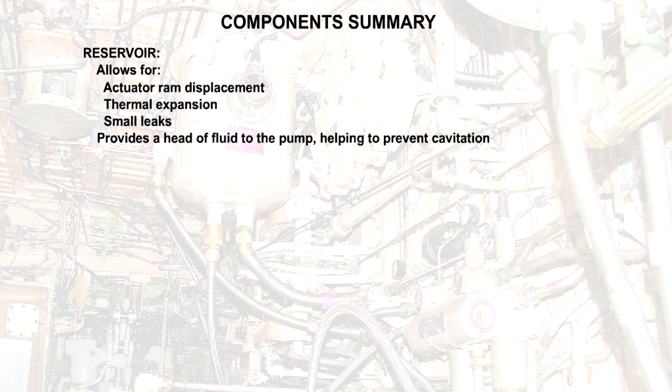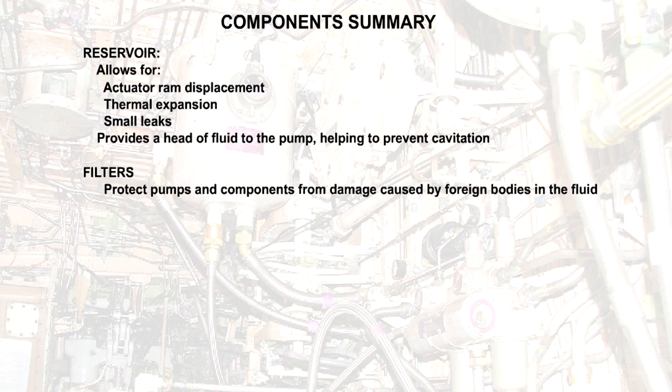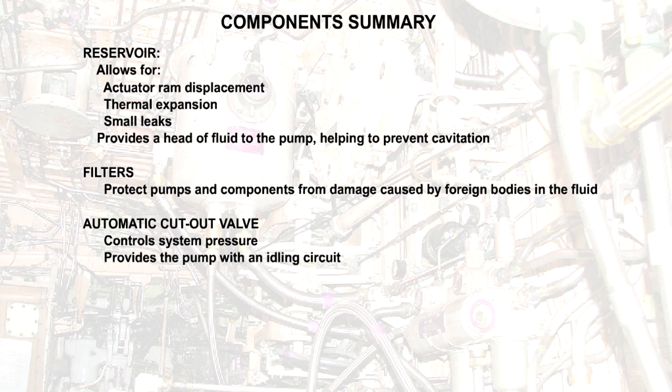Most reservoirs are pressurized to provide a positive fluid pressure at the pump inlet in order to help prevent cavitation. Filters are used to protect pumps and other system components from damage caused by foreign particles in the fluid. An automatic cut-out valve is fitted to a system employing a constant delivery fixed volume pump to control system pressure and to provide the pump with an idling circuit when no services have been selected.